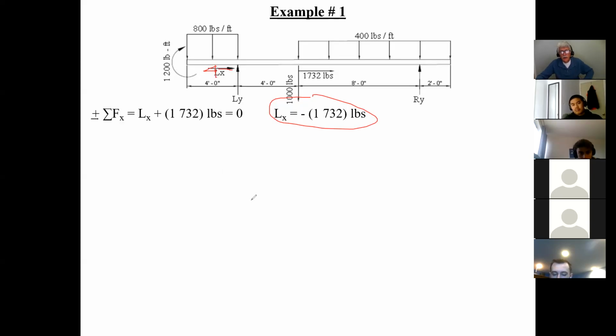So what this means is that from this point of the beam here to this point of the beam here, I will have an axial force. In other words, this will cause these fibers to go into tension this way. After that, here the axial force is going to be 0 because this is free to move. There's nothing to restrict it. So this is the only area of the beam that I will have axial forces because it's being prevented there and it's being acted upon there, okay?